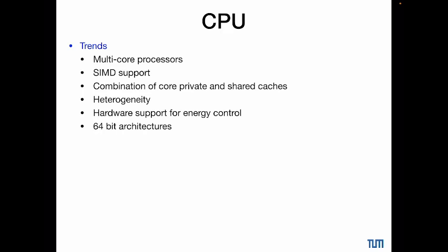And so to actually feed the processing power of the cores, we need faster memories, and so therefore in between the cores and the memory we have caches, and these caches are static memory compared to the dynamic memory of the main memory. And so this is faster, and so by that you can keep data that you frequently work with near to the registers, and therefore the processor can compute information faster.